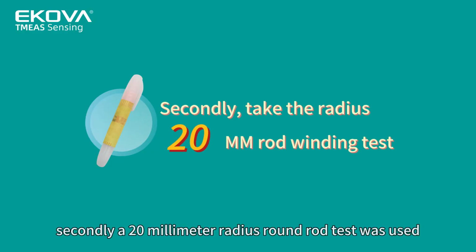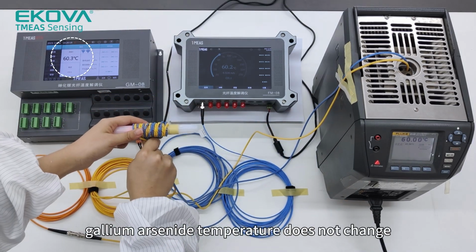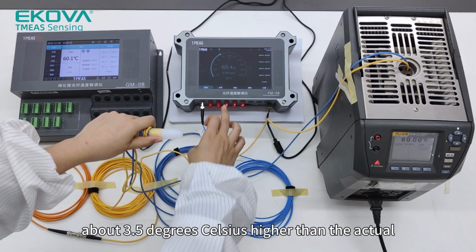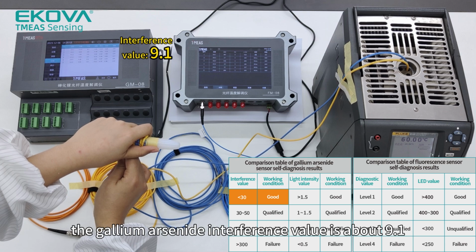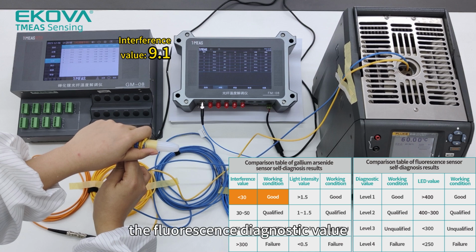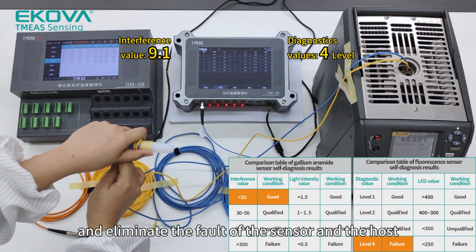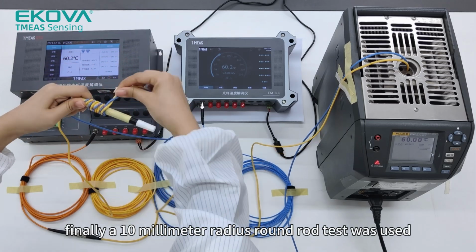Secondly, a 20 mm radius round rod test was used. At this bending radius, the gallium arsenide temperature does not change. The fluorescence temperature has been severely degraded, about 3.5 degrees Celsius higher than the actual. Look at the self-diagnosis results. The gallium arsenide interference value is about 9.1, almost unaffected, and the temperature is accurate. The fluorescence diagnostic value has dropped to the failure level. In actual use, in this case, it is necessary to stop the use and eliminate the fault of the sensor and the host.